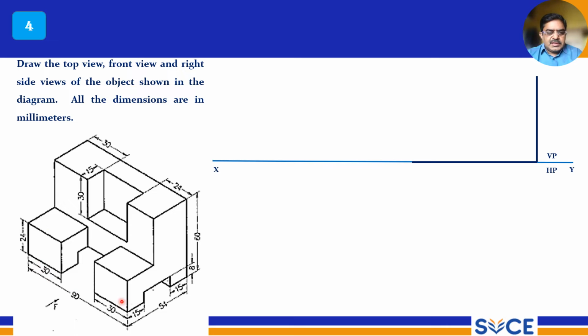Now this is the front view. On the left-hand side you leave space to accommodate your right side view. This is 90 mm, you draw a thick line 90 mm, and then it will look like a rectangle. This side is 30 mm, and this height is 24 mm. You draw this line, and then drop down, and this will be 30 mm, and this side also you draw here. And there is an edge at 8 mm.